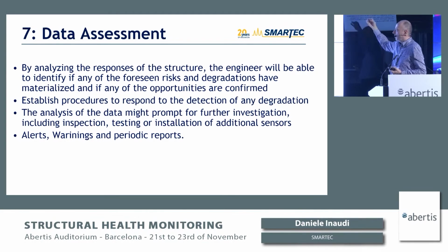If you have identified your risks correctly and you already know how they will become visible, then when you measure something, you can usually tell why you're measuring that change. For example, I'm measuring a tilt, and I was expecting a tilt if I had a settlement, so probably there's a settlement going on.